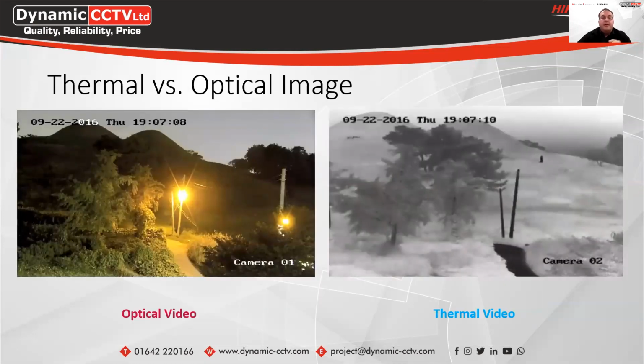What we have now is the thermal cameras. So specifically with optical cameras, if there's lighting in the image, you can struggle to see a person, especially at a long distance. Especially if there's light looking towards the camera, the image sensor can struggle with seeing beyond where that light is, especially in wide open areas as well. A thermal camera isn't affected by any lights in the area, as it is looking for heat sources.